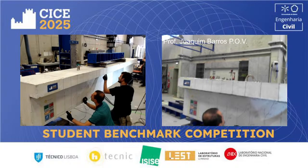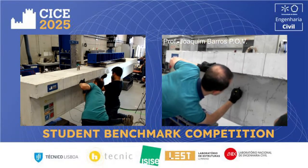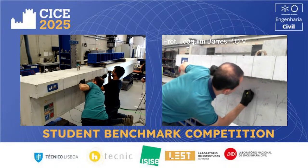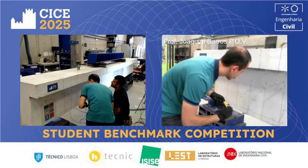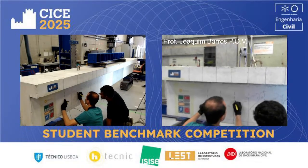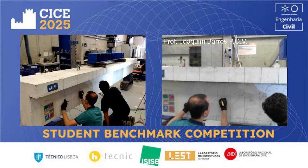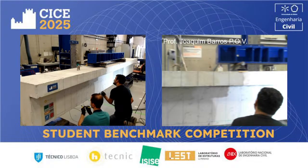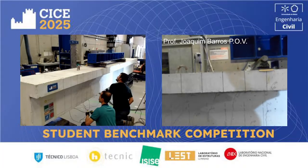As you see, the closer the cracks are to the support, the more inclined they are, due to the predominance of the shear load. Remember, the shear is constant in this shear span, but the bending moment is increasing from 0 at the support up to the maximum at the loaded section.